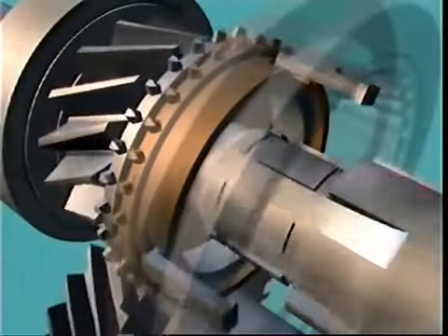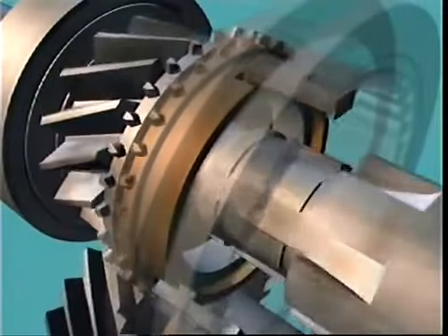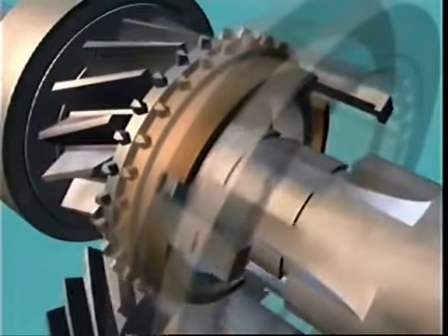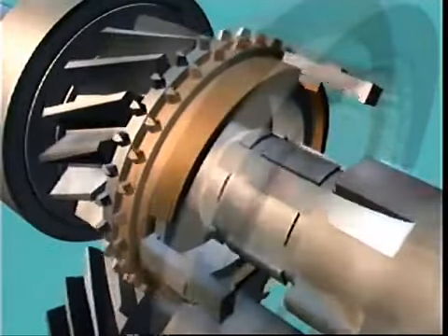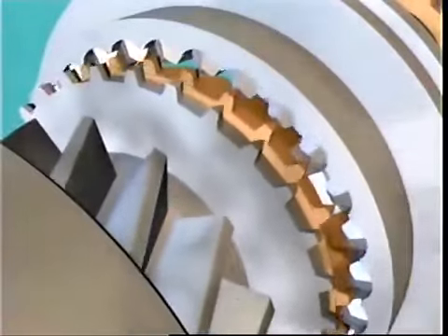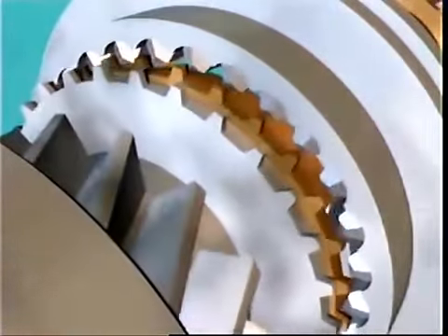The grooves in the face of the Bork ring help to break through the oil film, and the difference in speed of the two components causes the Bork ring to be dragged around with the gear to the limit of the recesses, where it is held by the inserts. Since the teeth of the Bork ring are now out of alignment with the teeth of the sleeve, this balks or prevents the sleeve from moving over the ring into engagement.